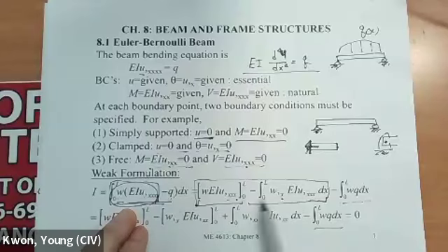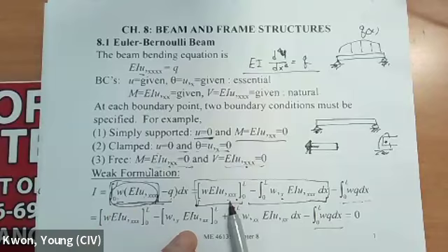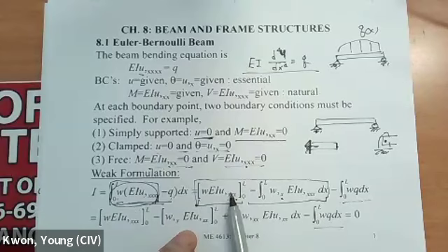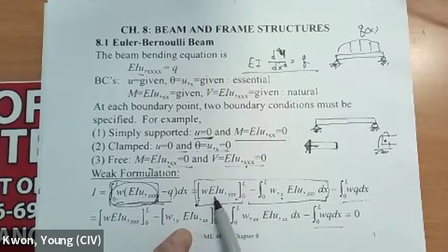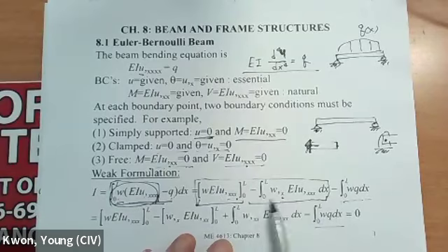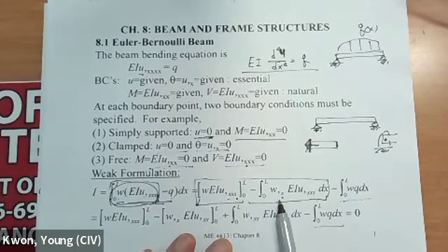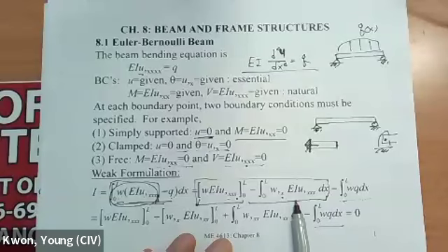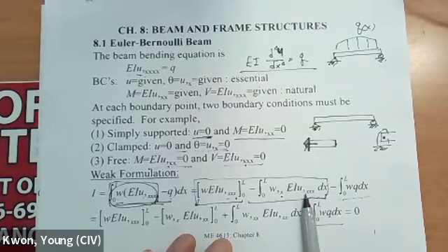Okay, this is the boundary integral between x equals 0 and x equals L. It's just a point evaluation at the left and right ends, so we don't have to worry about it right now. But this is the domain integral. Look at that: the test function requires a first order derivative, while this requires a third order derivative. There is still an imbalance between the two. This is going to dictate the choice of the test function or trial function in Galerkin's technique.